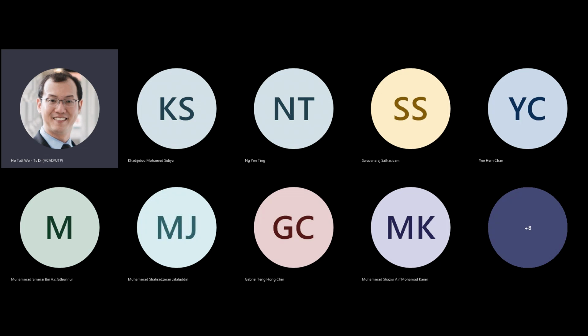But you have a little bit of slop, right? What I'm trying to say is that this can actually compute maybe in like 10 nanoseconds, and this can compute like, let's say, 8 nanoseconds, right? They don't actually have to compute and arrive at their results at exactly the same time. Just as long as when these D flip-flops capture the computational value, they capture it at the same time, the results are available there.